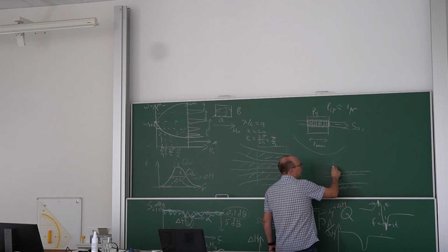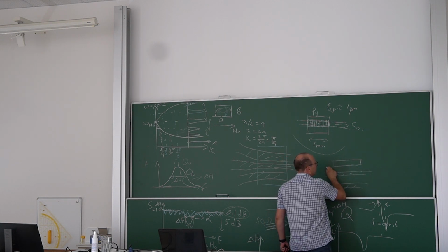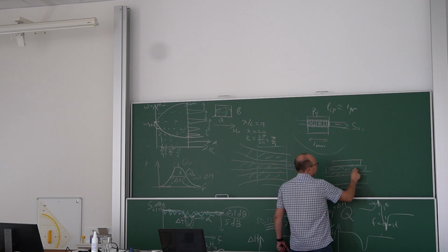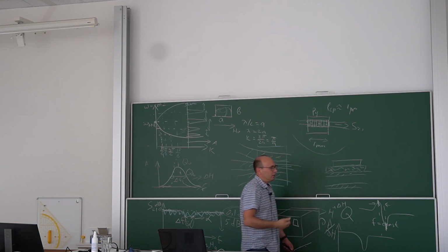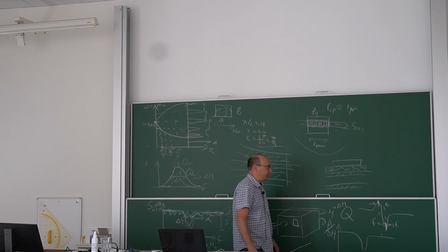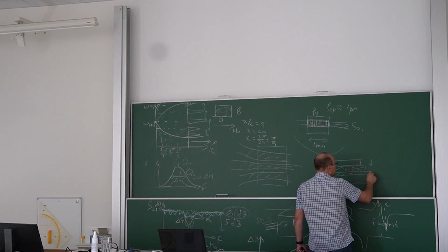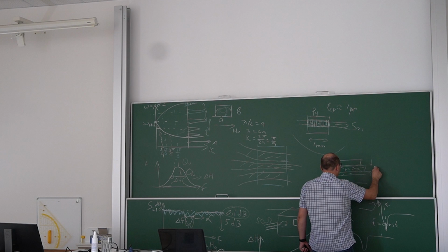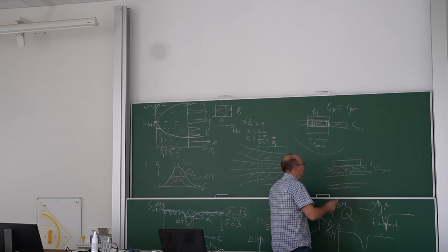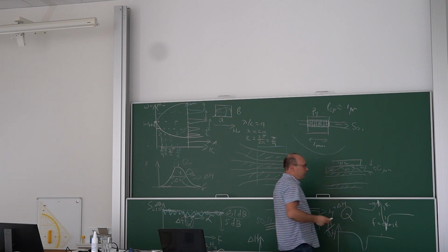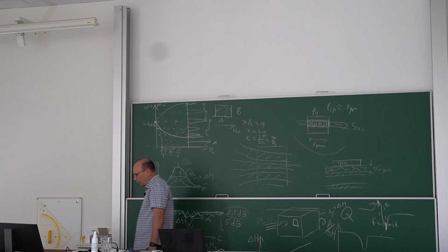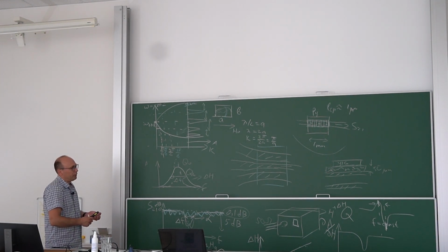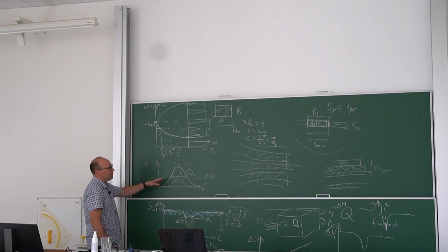You just put the sample not directly on a strip line, but you put some spacer, a piece of glass or anything transparent for the microwave field. The thickness you need to check, but in principle, let's say 50 micron, maybe less, maybe more. And if this is your YIG, then what you do is check if the signal matters for you, because it also depends on many different factors. For experimentalists, it's always easier to check rather than to calculate.